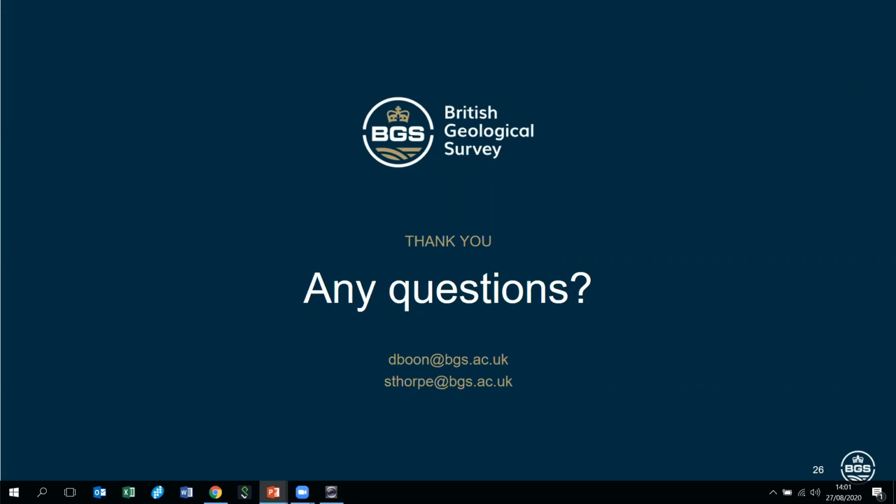Would you agree that looking at the BGS website and the different data sets, especially the ones you've shown today, is a good starting point for a project? But it doesn't get away from still needing to do ground surveys and getting out to site and doing actual TRTs and things. Yeah, I would say it's a great starting point for your desk study, which should be the first thing you're doing when you're looking at a new site. So get all the information together you can. There will be reports and things that we just don't have, so it's part of trawling around for the available information.